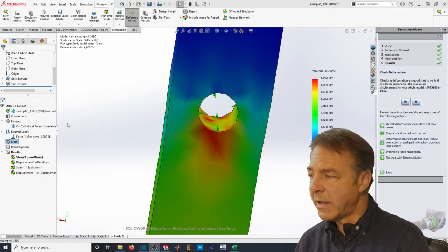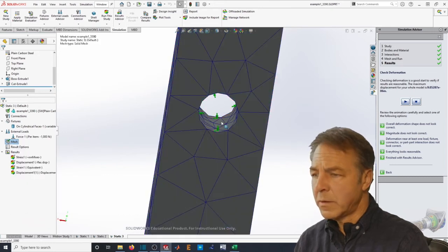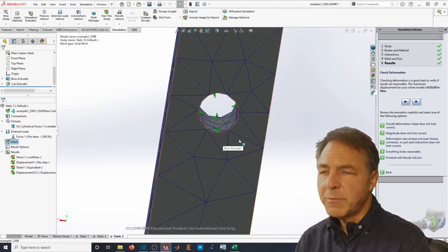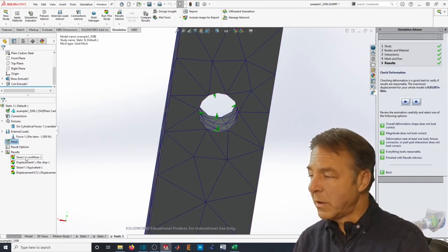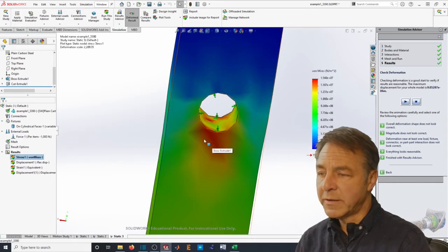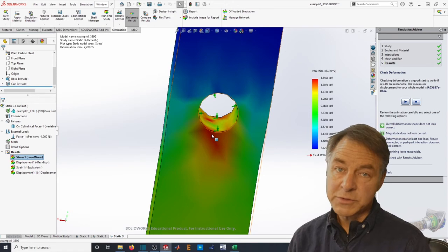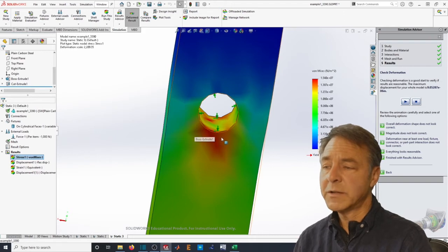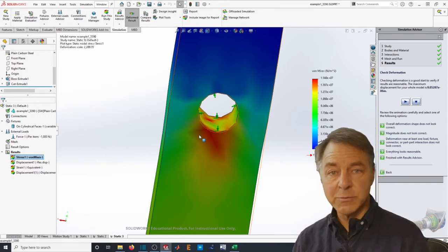Keep in mind that if you look at the grid or the mesh, we're really meshing this in such a way that there aren't very many finite elements around the hole. So that means that looking at this stress plot, a lot of the detail in here is smaller than the size of the finite elements that were used to solve the problem, which makes me skeptical that it's realistic, because it's really showing features that are smaller than it has any right to be claiming.